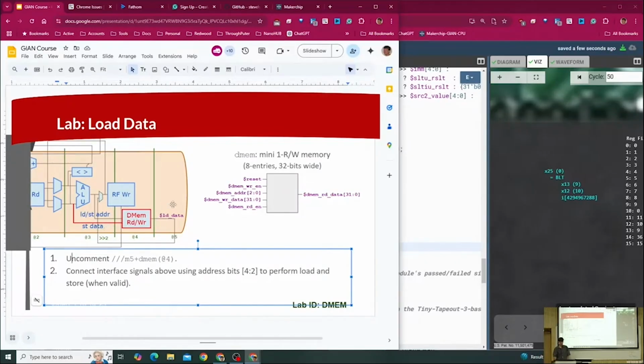So then when we recirculate that into the register file, the recirculation into the register file, right, is looking 2 cycles ahead in the pipeline for the load data at stage 5. You're going to get different staging of that data, right? If we were to assign that as an add 3, that would get staged an additional 2 cycles. It really is associated with add 4. It should be staged just 1 cycle.